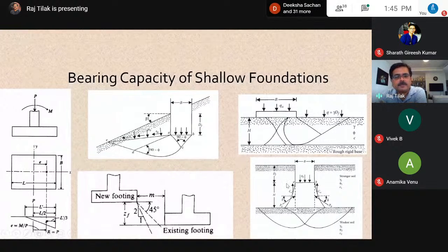How do you make the case that this is not going to work? You will have to use a much lower bearing capacity as compared to what is typically recommended. And he will not be ready because his cost will go up. So you should be able to analyze all these things. There was an instance where I had to recommend piles, even though the top 4 or 5 meters looked perfectly all right. So it was a big challenge. These things do happen.